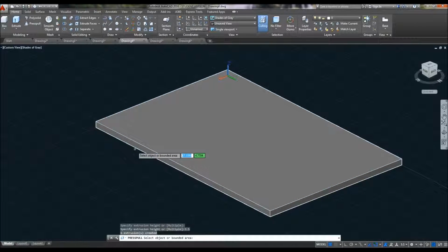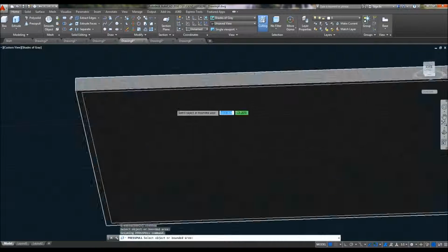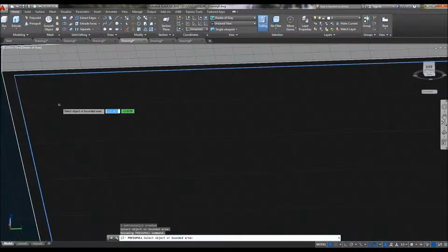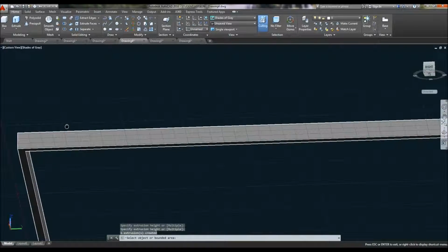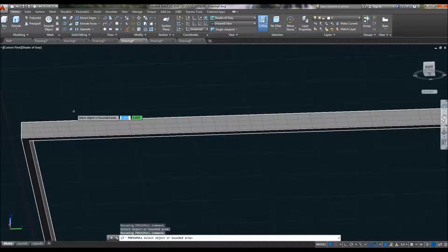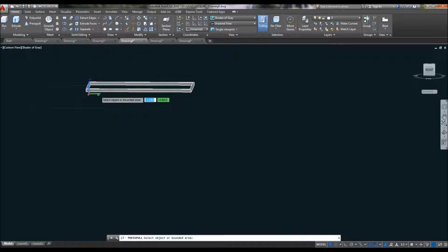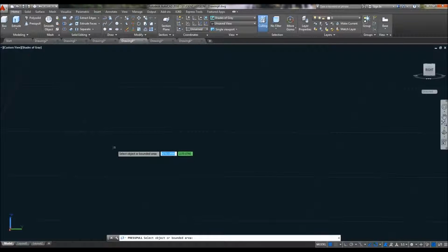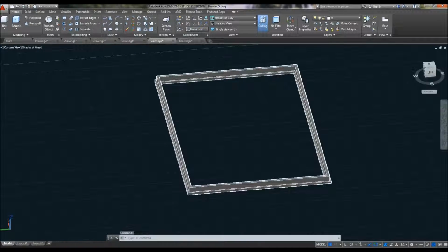So now it's 3.5, and you want to click your mouse wheel with shift, and when you go underneath the object, make sure press pull is still on, take the bottom, and go up through. Now you have the part that you want. Then you want to escape and zoom out, and pull up the other part, and it'll look a little like drawing 5, which is this.